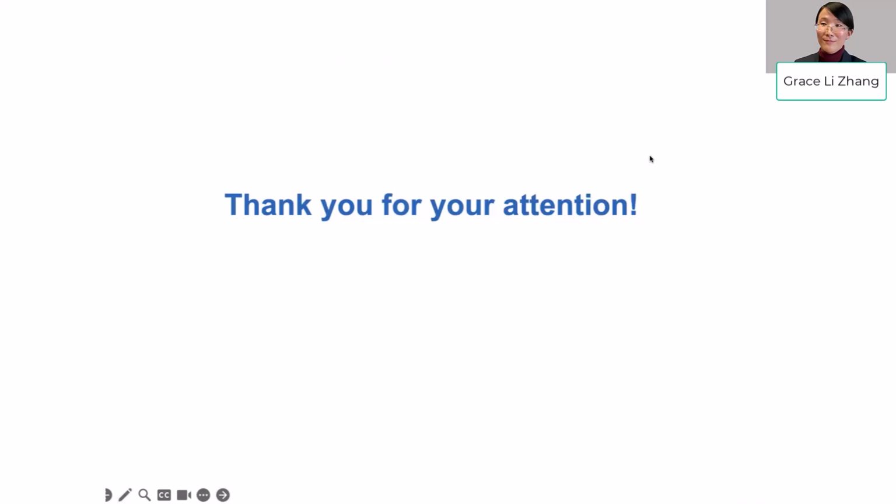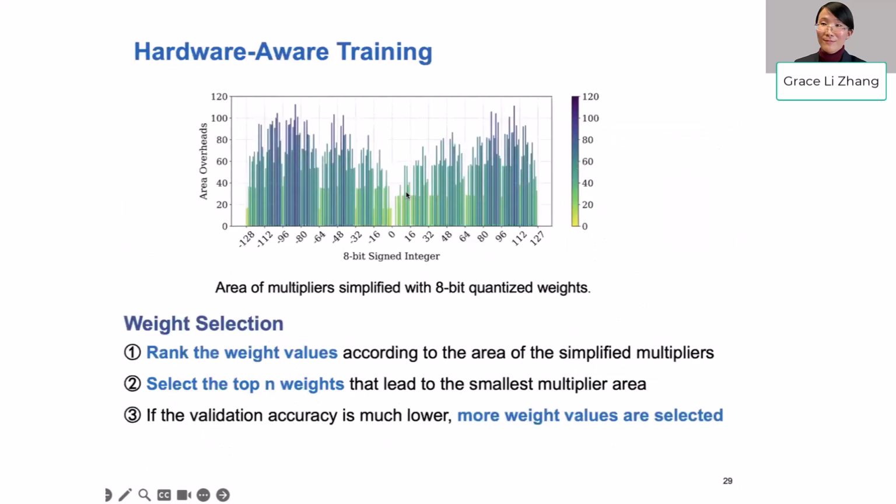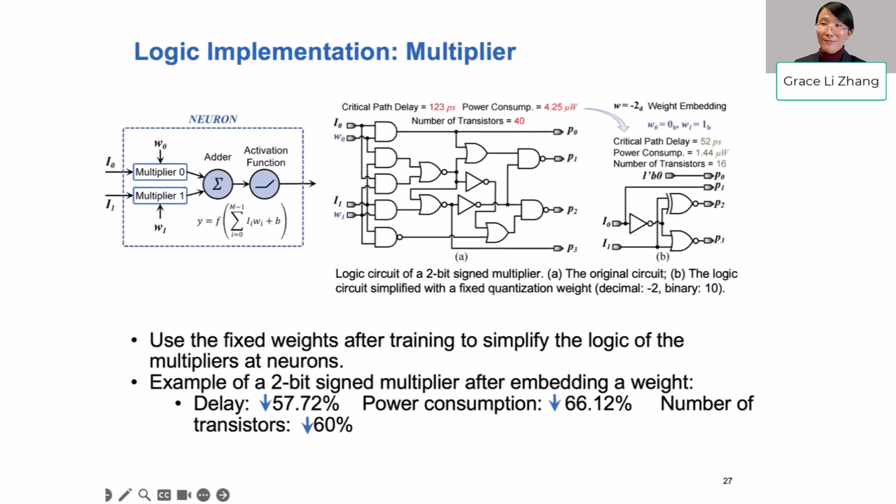Yeah, I had a question, actually several, but I'll just go with one for now, in the section regarding the logic-based design for neural networks. Yeah, this one, right? Yes, exactly. So I just want to make sure I understood that correctly. Is this essentially designing an ASIC based on weights that have already been trained? Yes, you can target ASIC, or you can implement the circuit on FPGA so that you can still switch the applications. Right, okay. So a programmable circuit, essentially. Yeah. Okay, but the circuit structure is obviously based on the weights that have already been trained. Yes.